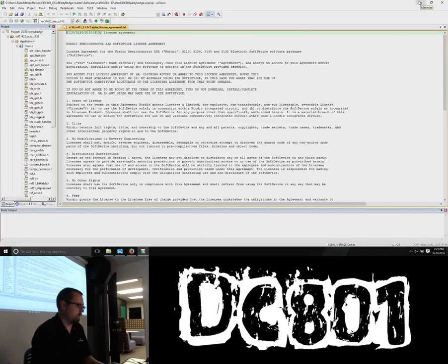Oh, okay. Well, I remember you told me there were two files, right? There's the soft device, and then there's the hex. It's the actual program code. The code. Yeah. So that's the application, I guess. The application. So this is like your firmware and then your application that runs on top. So your bootloader, kind of your OS per se, is your soft device, which determines your functionality. Then your application utilizes that firmware to run its application. So it's kind of like an operating system. Yeah. Briefly.